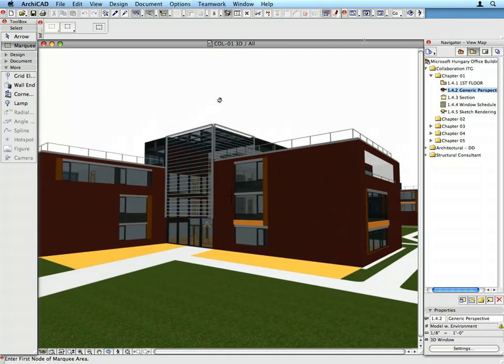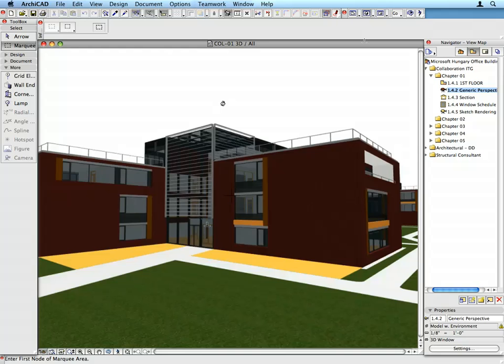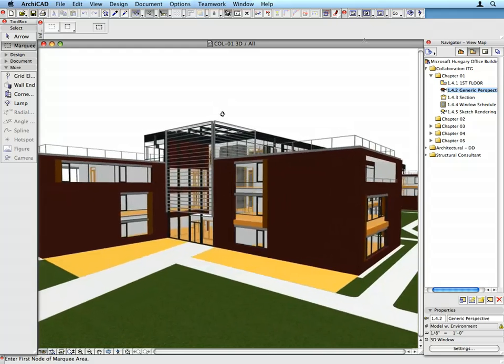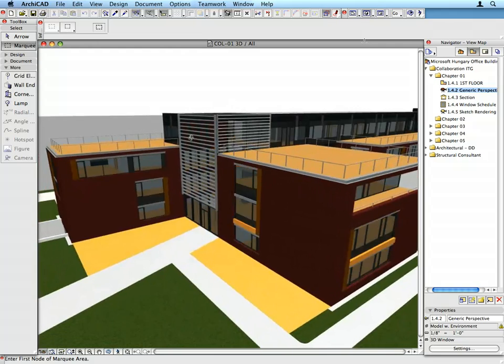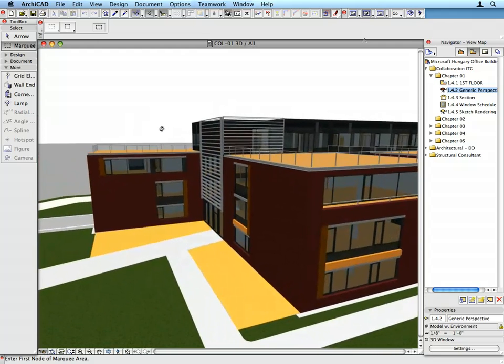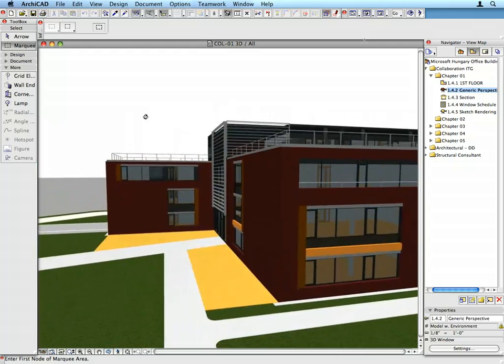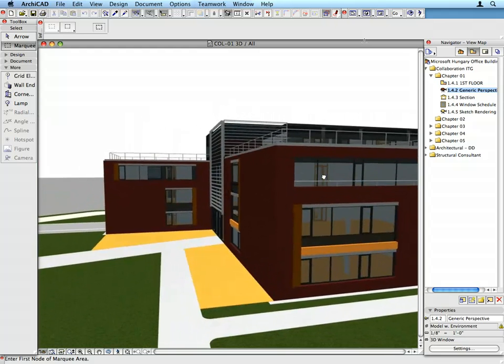Now, hold down the Shift key on your keyboard, and also hold down your mouse's middle button or scroll wheel. The mouse cursor changes to a different cursor shape, showing that you have entered the orbit mode. Move your mouse around to orbit around the 3D model. As you can see, you can freely rotate the model in 3D. Do some orbiting to get a general idea of how it behaves.